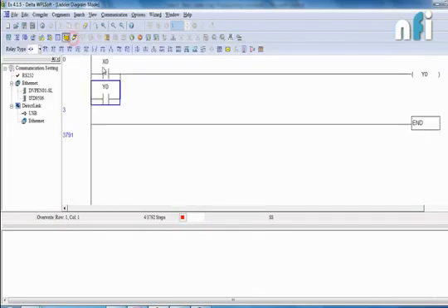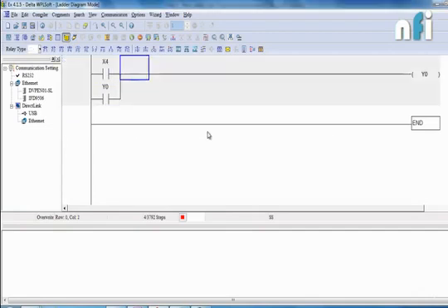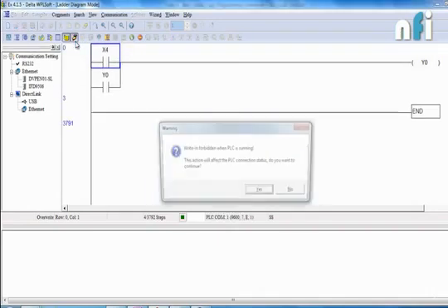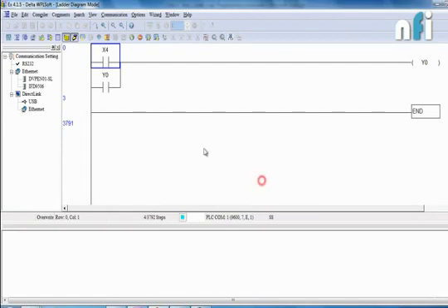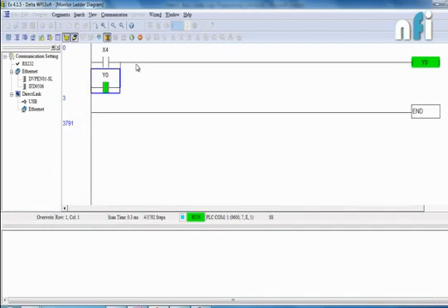Our question was to use X4, which is a push button, to perform this experiment. I have used X4, a push button, which I'll push, as you can see in the trainer. When I press it, Y0 remains on. When I release it, Y0 remains on because it has latched itself using its auxiliary contact. The next situation was that I have to press X5 to unlatch it. It means to switch it off, I have to use a button X5.